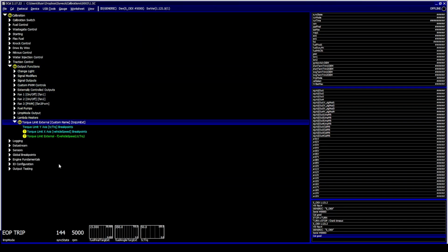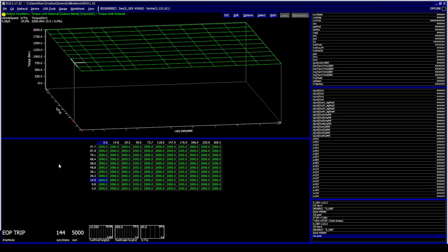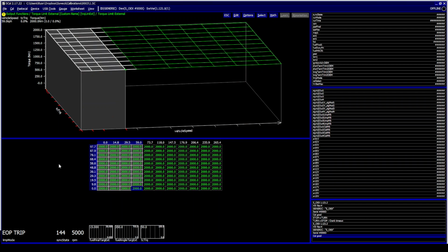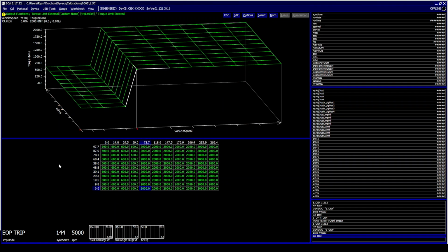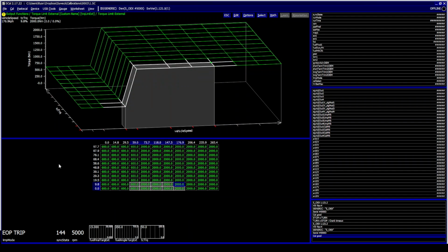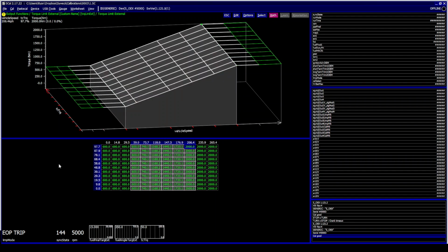And then based on your speed and torque reduction amount, you could set an overall torque limit. So you could say, okay, I want the torque to be clamped below, say, 600 Newton meters, and then after that, want it to go up with speed.